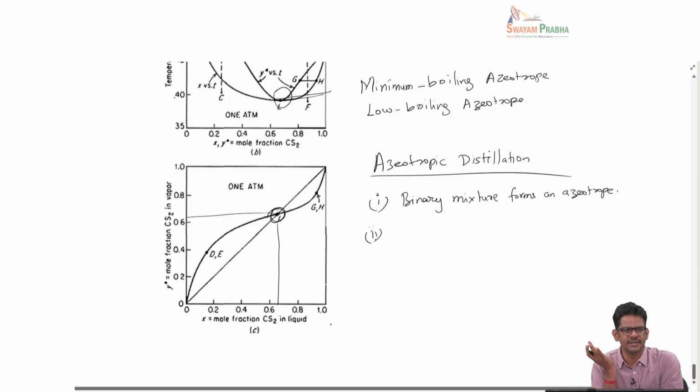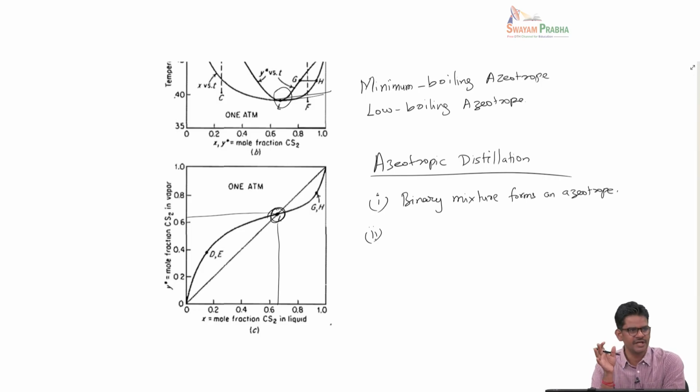Why there is an azeotrope, and whether an azeotrope will always form, are determined purely by thermodynamics, which encodes the mutual interactions and the ideality and non-ideality of the constituents. The azeotrope may be present at certain temperature and pressure, and it may vanish at another pressure. So you have to look in detail at what the thermodynamics tells about this binary mixture. A very well known example is the ethanol water system. It forms an azeotrope at 89.4%. Beyond that, the purification is very difficult.